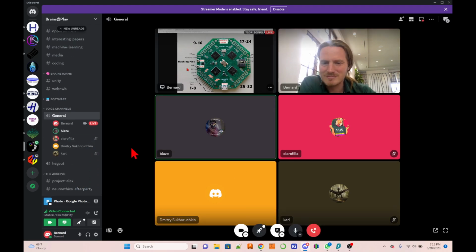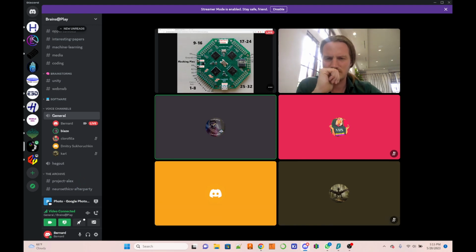I think also the typical thing is you use all the bottom ones. At least what I've seen, you plug in SRB1 as your ground lead in essence, and then you put your signal into the bottom, which are on the negative. Whereas here, the positives are on the outside, which I've got the pre-soldered ones, so they're on the bottom. So I'm still plugging my signal into the bottom, except it's going into the positive pin rather than the negative pin. That makes sense. I'm wiring it the same way, but I'm actually putting it into the positive pin, your red lead on your multimeter, which makes more sense to me. Unless I've got that the wrong way around again, but I can check my notes.